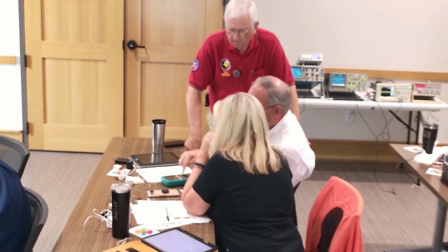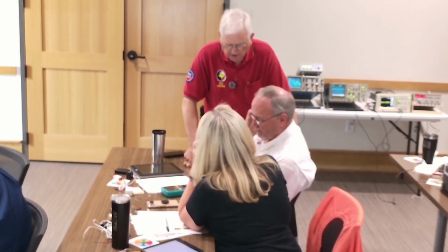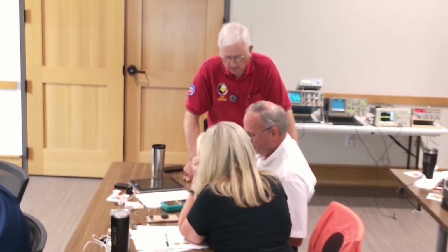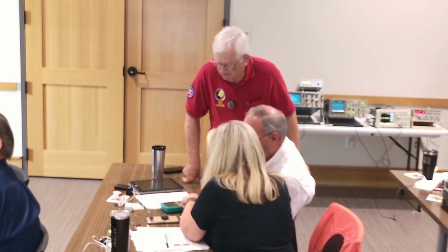Can I hurt a meter by having it set on the wrong range? No, it won't hurt anything. It just won't read right. So you start at the highest, obviously, so you don't blow it up, and go down until you find the one that matches.